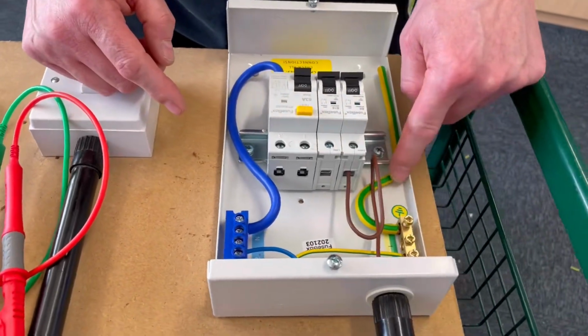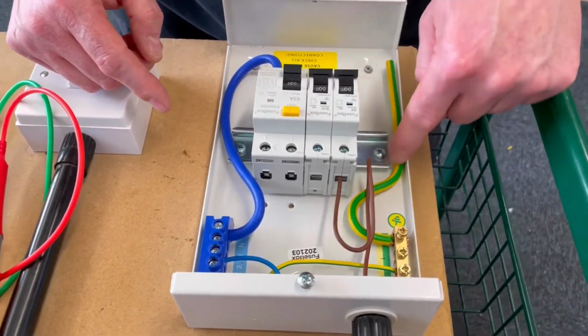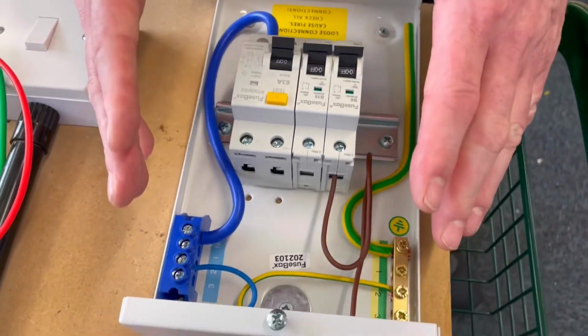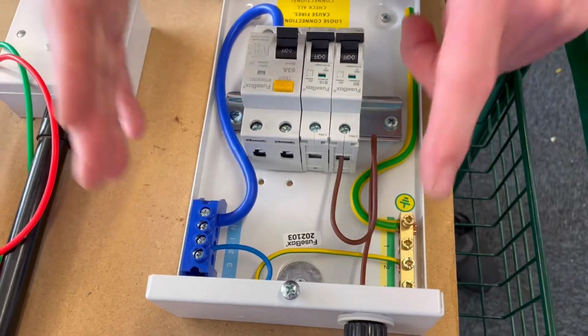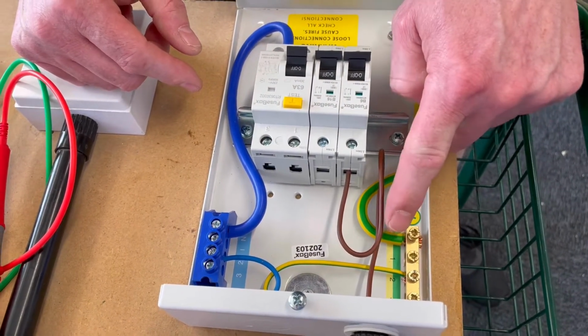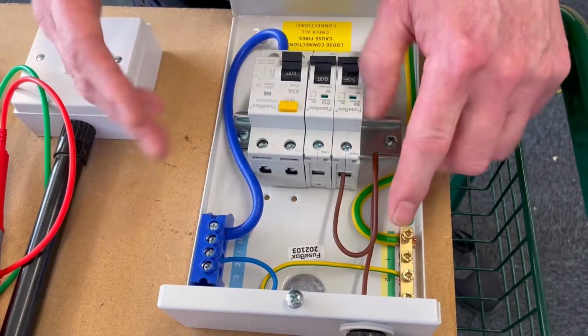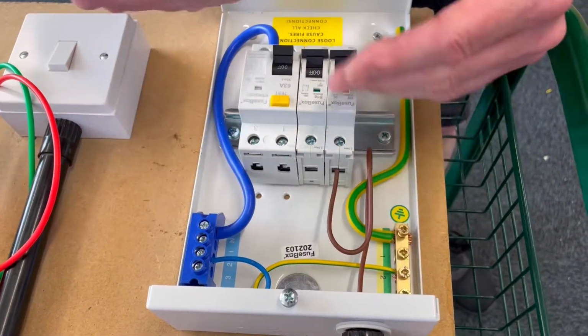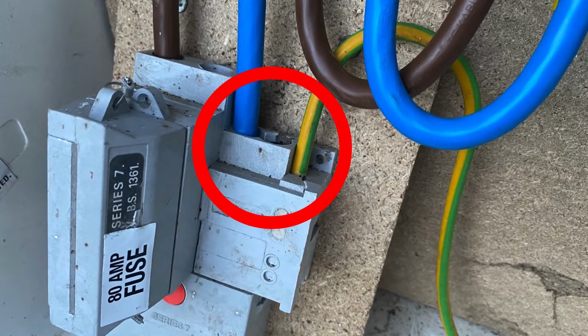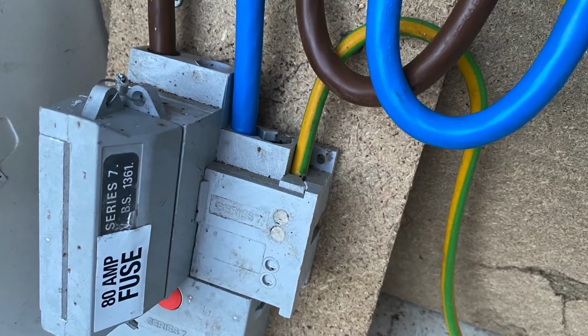Now, I've left one little conductor here, which you can see doesn't go anywhere, for a reason. This is to remind you that when carrying out the insulation resistance test, the earthing conductor, which comes in with the tails, must be connected to the source earth, as well as any bonding. So in a TN-C-S earthing arrangement, this green and yellow conductor would go off and be connected to the cutout where the neutral is.